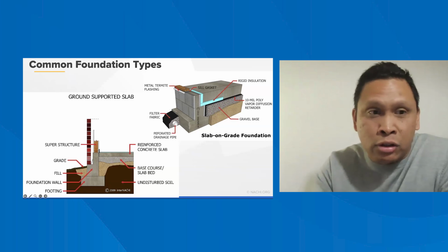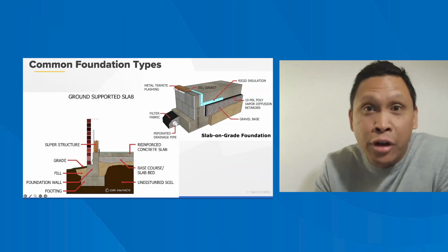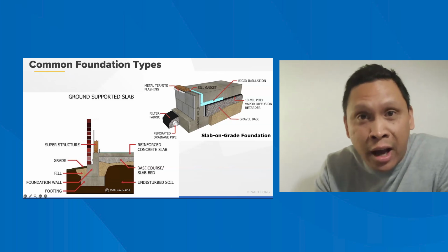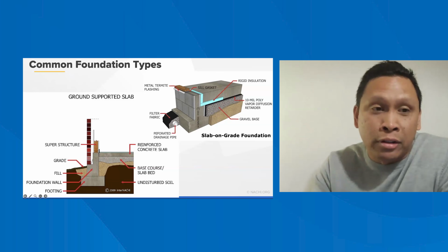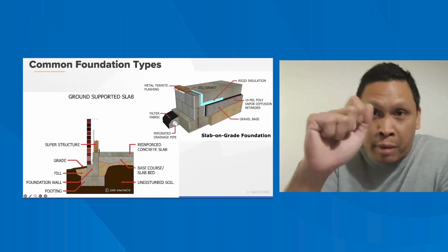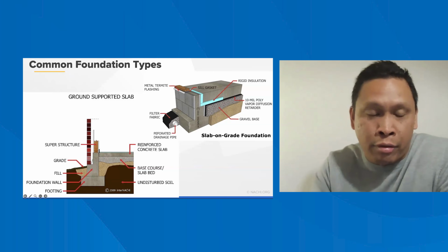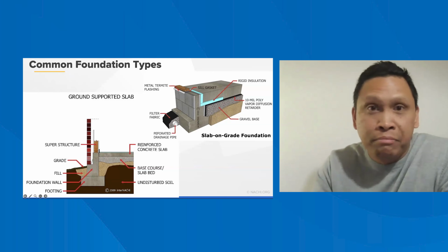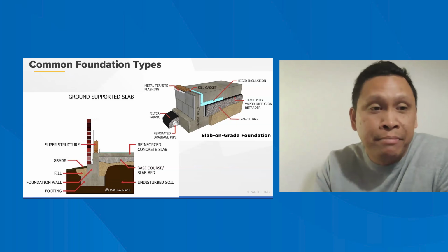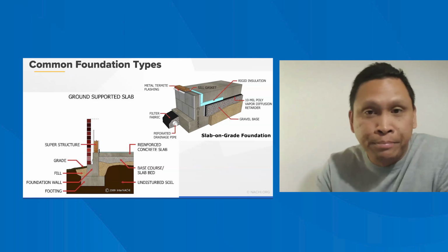But when I was able to finally squeeze my head in there, do you think they had all the nails installed on both the left and right face? No, they only had one on each side. It's a joist hanger. So very, very important to take your time. Oh, and then I was able to squeeze my camera through. I was holding my phone, and tried to wiggle my way through to the other joist, and same thing, one on each side. It happens. They forgot to tack them up. So take your time. It's important.